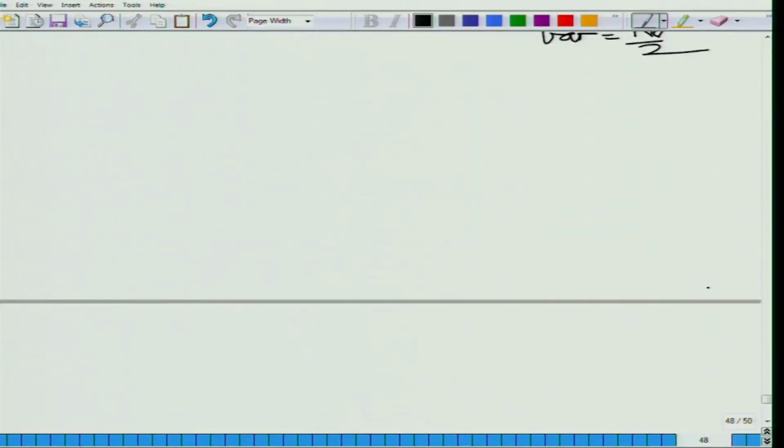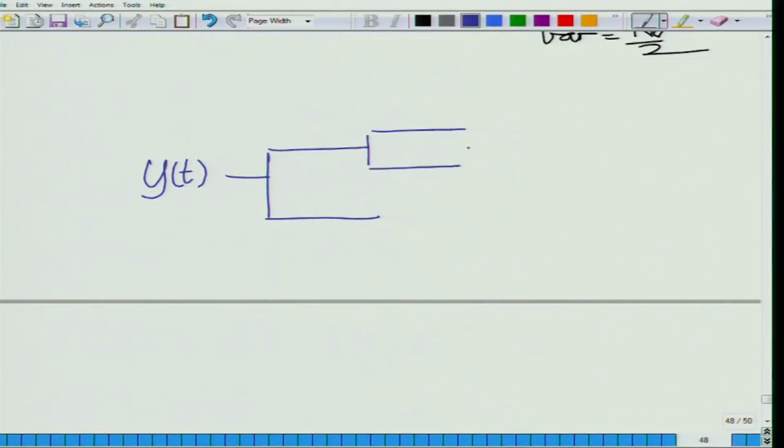Okay. So, basically if I have to represent this schematically, we have this incoming signal, not x(t), we have this y(t). We can now represent this as two separate branches, one for each matched filter. So, you matched filter with H1 t, where H1 t equals P1 of T minus t.